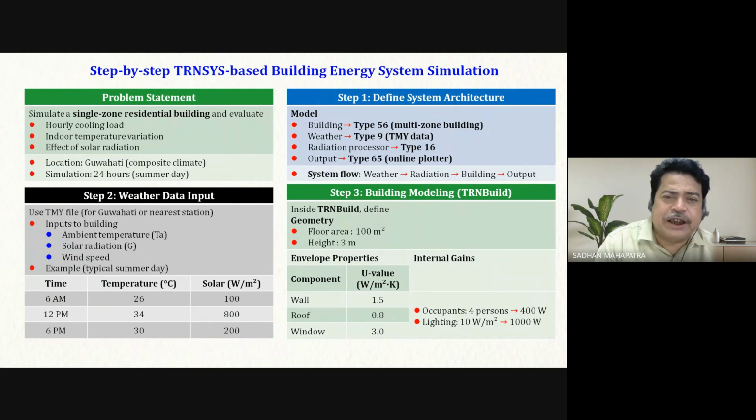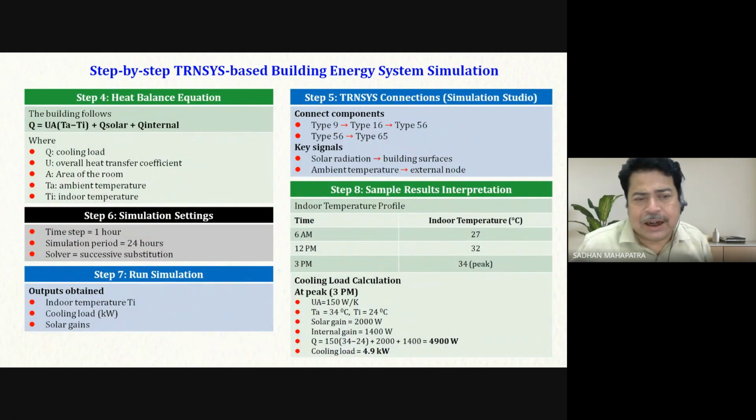Here is the step by step process for the building simulation using TRNSYS. Simulate a single zone residential building and evaluate hourly cooling load, indoor temperature variation, and the effect of solar radiation. Say the location is Guwahati, and the simulation is 24 hours. Step 1, define the system architecture. Step 2, weather data input. Step 3 is the building modeling. Step 4, the heat balance equation.